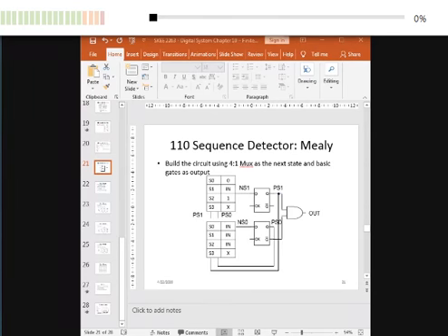You cannot simply go straight from the output of the multiplier and then display on the 7 segment. No, it's not that simple. Maybe you need another processor, your BCD, if you want to show the result in decimal.